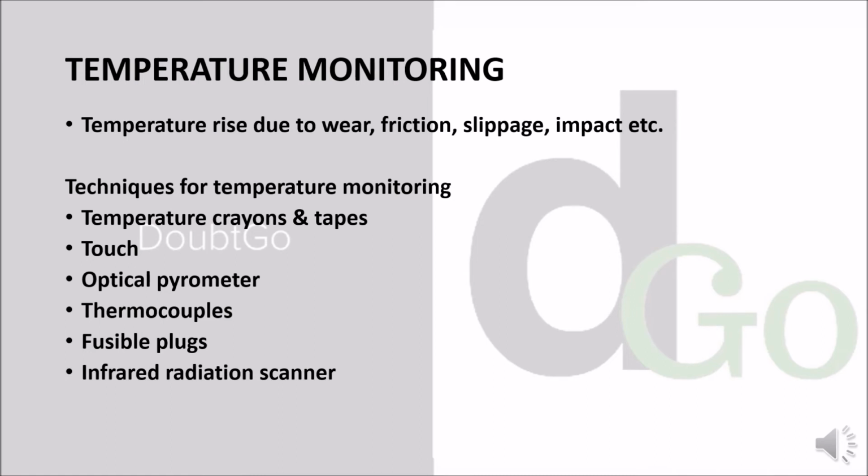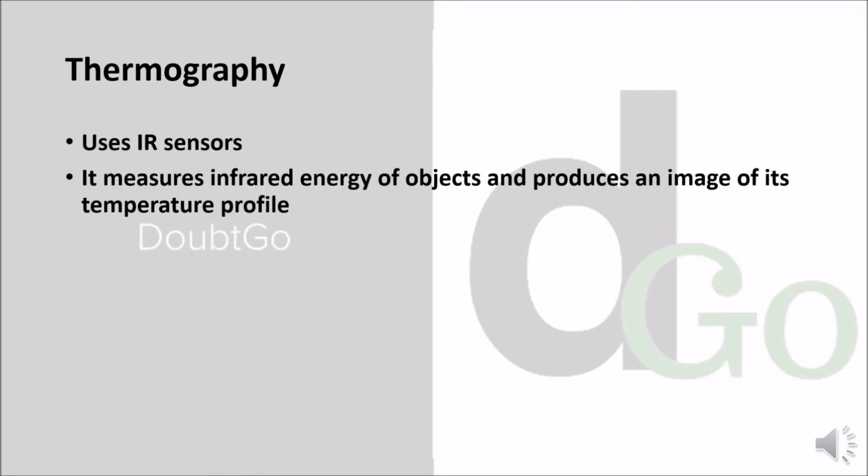Infrared scanners and resistance temperature detectors. Thermography uses infrared sensors. The infrared sensors measure the energy of an object's surface and produce a detailed visual image that depicts its temperature profile. It is a safe, cost-effective and non-destructive type of test.